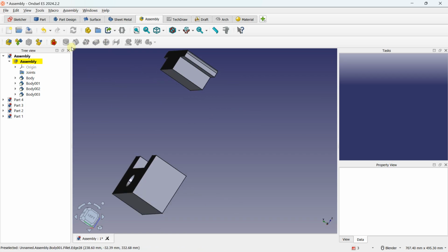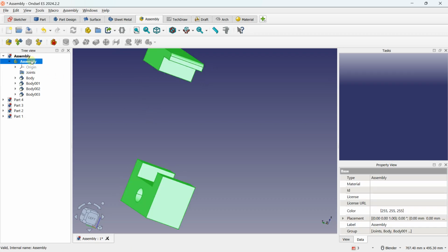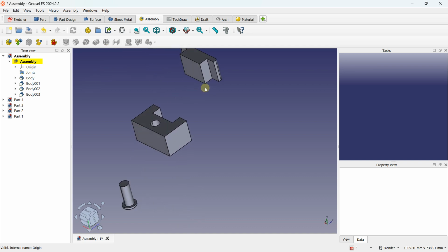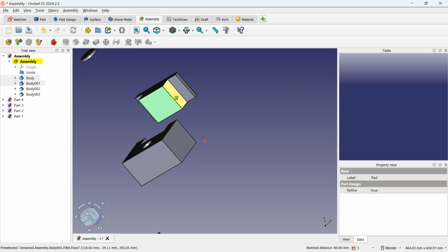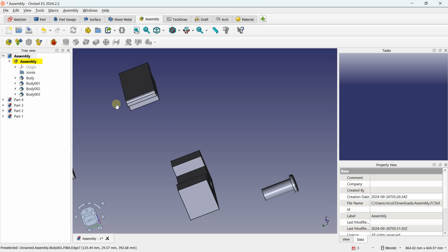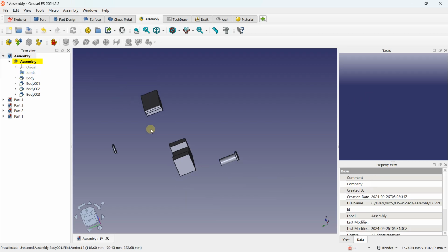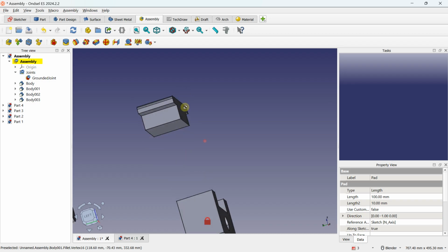I can also double click on my assembly just here. Double click on my assembly and try another one. So select again this face. Select again this face and this face. And one of the problems is when I go in this area, I need to double click on my assembly. I need to check something first. So when it's like this, it's not possible to edit anything. You need to unlock the toggle. And now I can have access again to these different options.